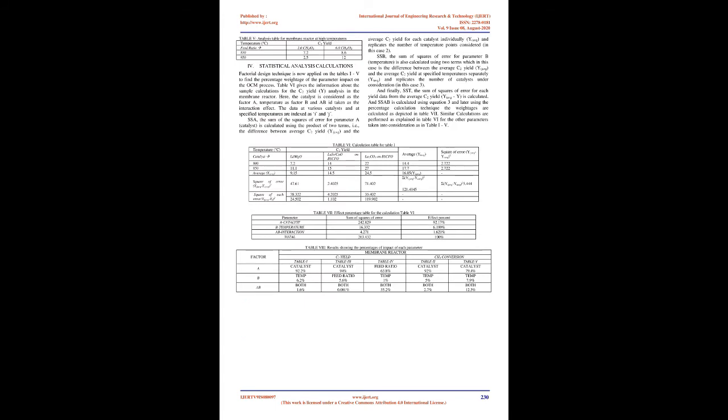His conclusions also stated that the selectivity of C2 hydrocarbons exceeds 60% and 40% for the reactors with LaSr/CaO and Sr/La2O3 catalysts. The most attractive feature of his research work was that the catalysts employed gave higher selectivity at lower temperatures, which is quite hard to achieve. From further evaluation, he also concluded that the selectivity of Sr/La2O3 has no significance, as it is much less compared to the bare membrane used at 800 °C, 1073 K, whereas LaSr/CaO allows a selectivity of about 40% at the same temperature under considerable conditions. His conclusions were highly rated as they gave a complete guide for the choice of the best catalyst.